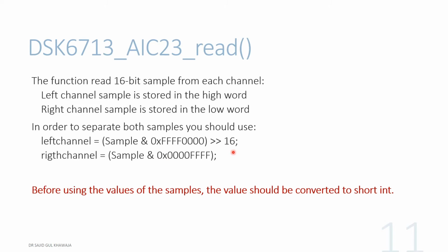Finally, we also need to consider that the definition of left channel and right channel be in such a manner that they make use of only 16 bits each. This can be managed by defining the left channel and right channel as short int instead of utilizing int32.